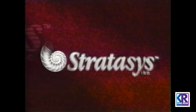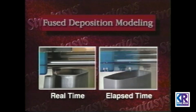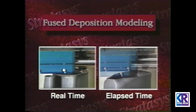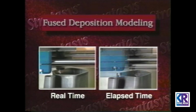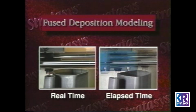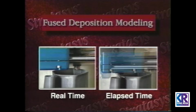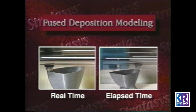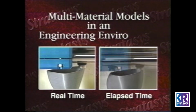A second process for die-less fabrication of a wax pattern from an electronic design uses a process known as fused deposition modeling. This process also separates the model into horizontal slices and builds the part by successive layering. A wax wire filament is extruded through a fine capillary attached to a numerically controlled XY positioner. A heater on the head keeps the wax just above its melting temperature. As the head moves along a path defined by a particular horizontal slice of the part, the wax is precisely extruded out of the capillary.